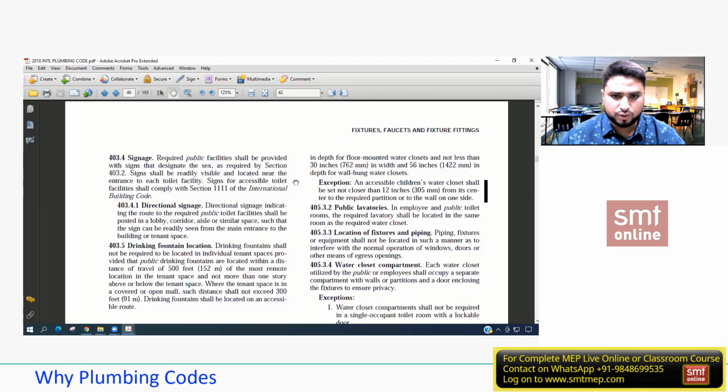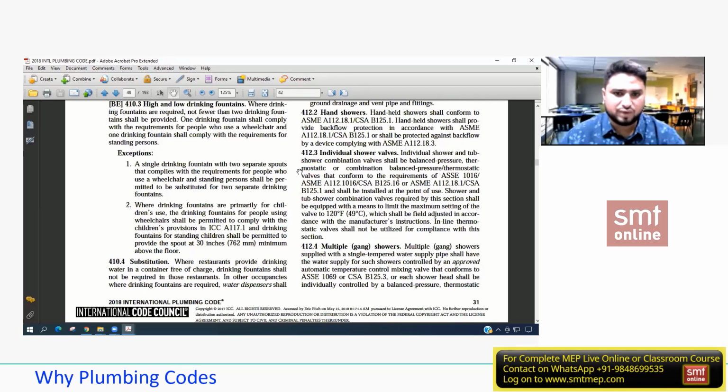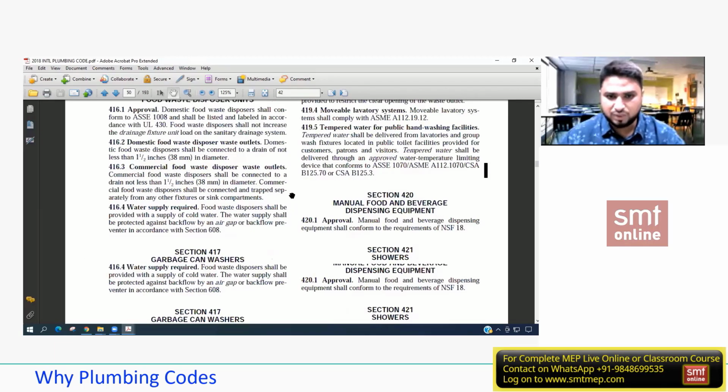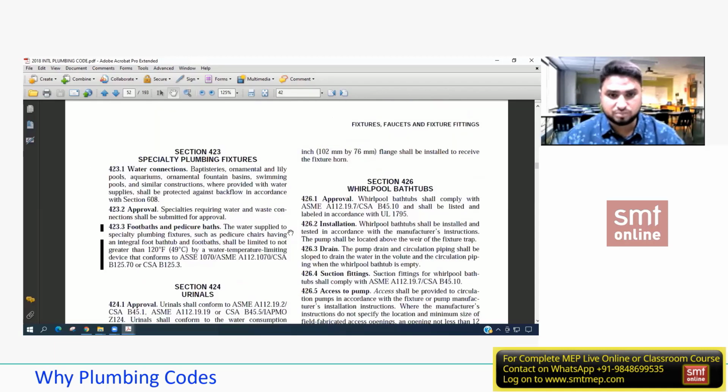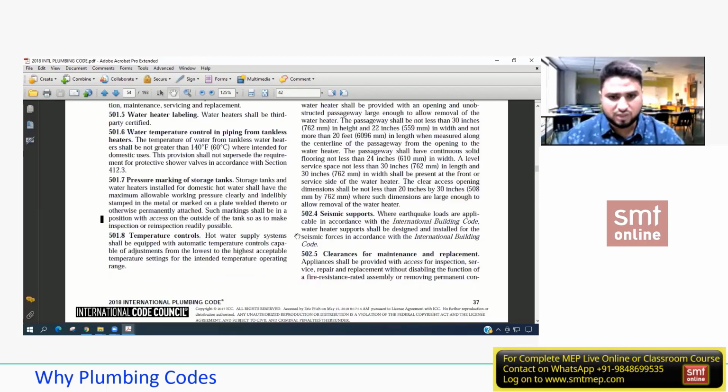I have 2-3 more things to show you, and most importantly, we are here to find out the main pipe sizes, not the branch pipe sizes. Branch pipes are the pipes connected directly to the fixture. Those sizes are also predefined, which means they are given directly from the codes. One can find them out the same way.